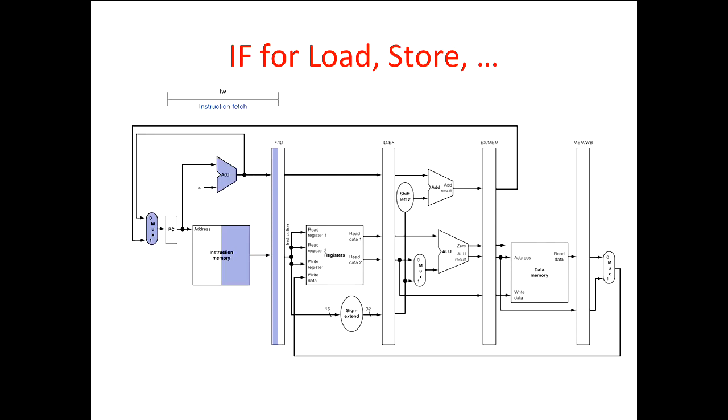So notice this add happens here, and we mux in PC plus 4, so that the next clock cycle we know where the next instruction to be fetched is, right? So we can do all that in one of the pipeline clock cycles, so that we can start fetching the next instruction straight away. And we'll come back to what happens in branches a bit later on. This is just a simple case where we're just going straight through the code.